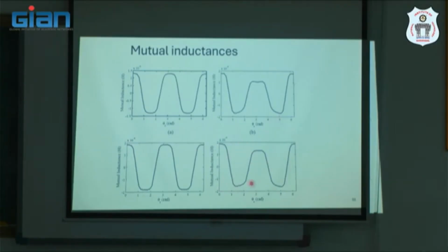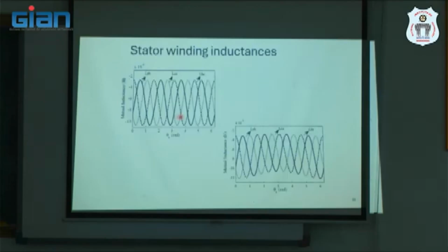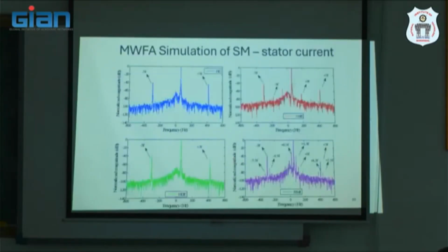So this is how you will synthesize inductance. And these are the stator self-inductances, basically L_AA, L_BB, L_CC. And these are mutual inductances of the stator windings, L_AB, L_AC, and L_BC, under a healthy condition and a mixed eccentric condition. So they are completely position dependent. So you can use them to simulate. But this approach is very sophisticated, mathematically intensive, and therefore it's not as popular now as it was a few years ago. So now the most popular technique is